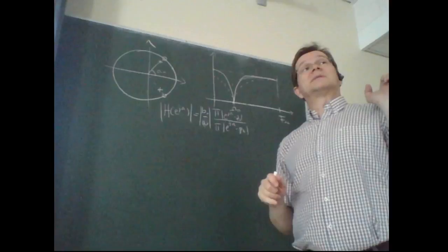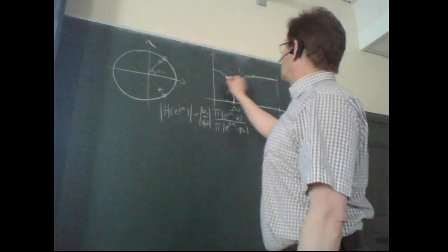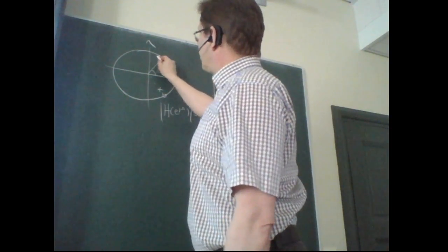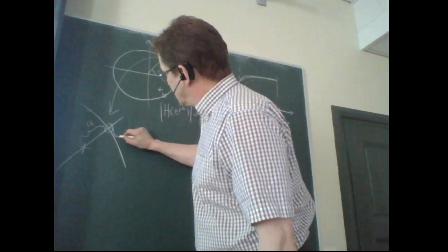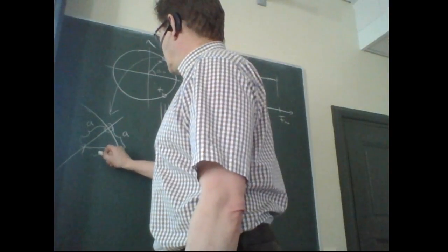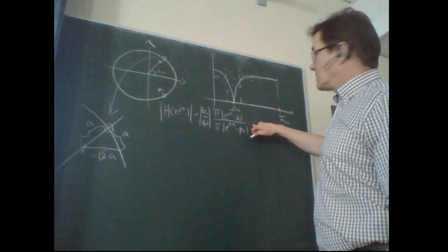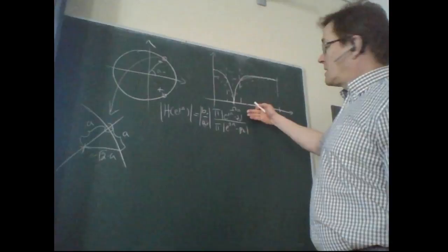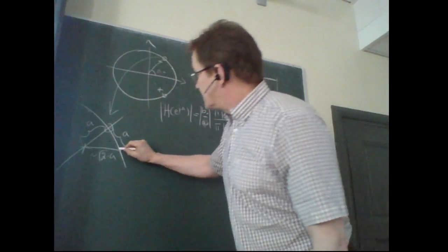This also has a control of the minus 3 dB point, since if you take a magnification of that one, and if this distance is a and you take the same distance here, this one actually becomes roughly square root of 2 times a, meaning that in this equation you will have a divided by square root 2 times a at this frequency.